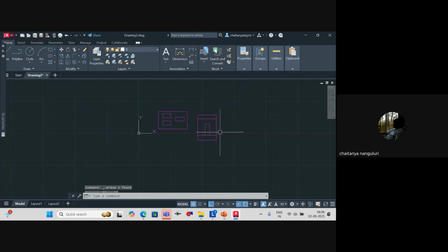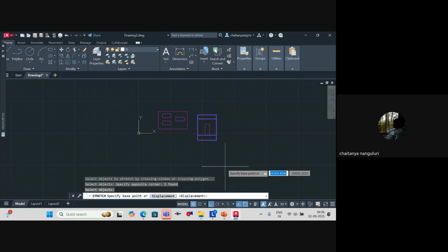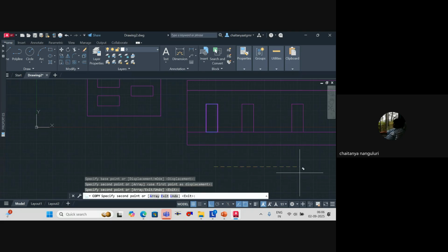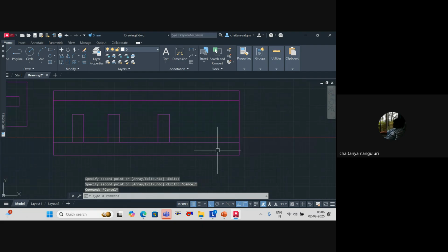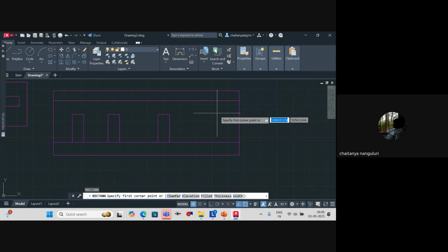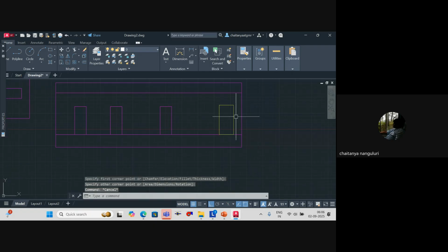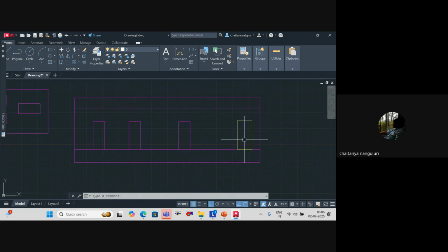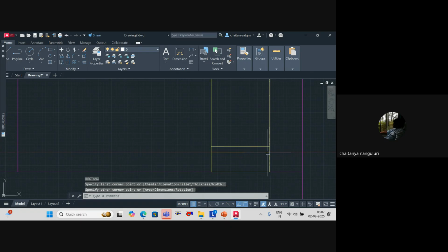So if you see a section, let's say this is your section, these are your server racks. What we do is we use other hardware called PACs, or precision control package air conditioners. Mostly we use it so that we can control proper RH as well. This is your PAC. This PAC will have a coil. So what will happen is this unit will throw air beneath, you'll have an airflow rate in this direction.